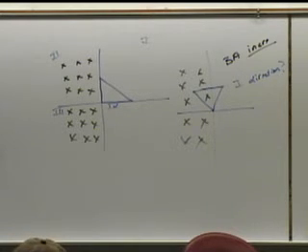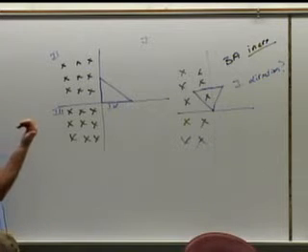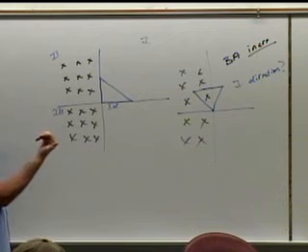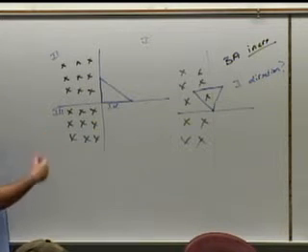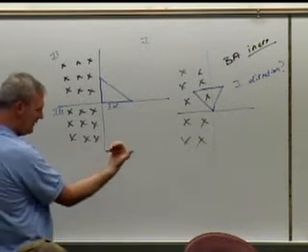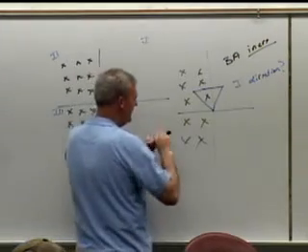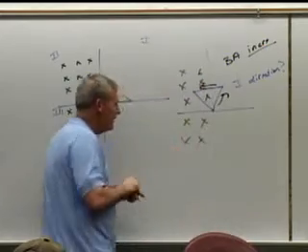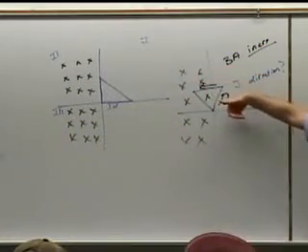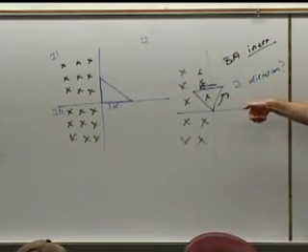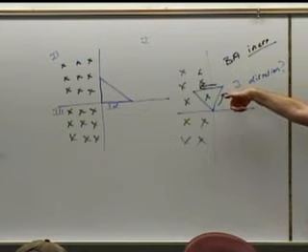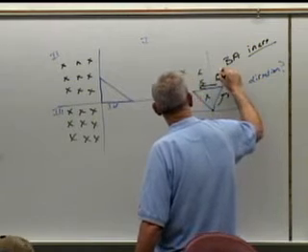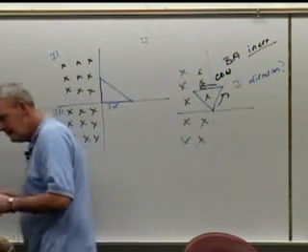Right. I want the magnetic field to come out of the board. So which way is that? Is that clockwise or counterclockwise? Yes. That's counterclockwise, because the current should be going like this. You got your current going that way, curl your fingers around, he's coming out of the board here. That's counterclockwise. Okay? CCW.